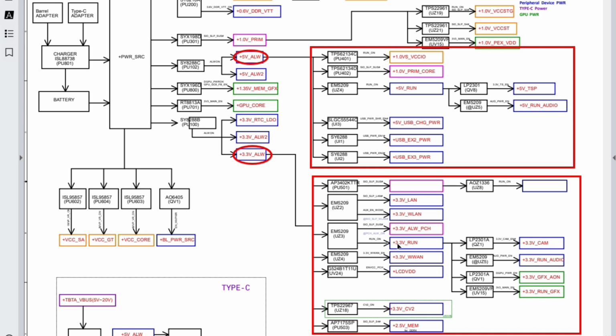About 95% of motherboard failures are due to these 2 voltages. Do you know that BIOS failures are due to this voltage, 3.3 volt? Because without 3.3 volt, the BIOS cannot work. Also, the power switch or the on-off button, its working voltage is plus 3.3 volt.